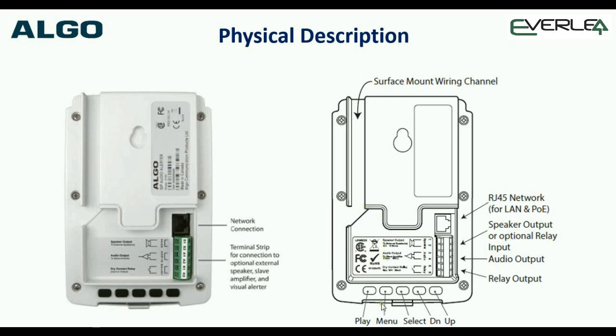The other way, if you've just plugged it in, is simply press this menu button here 3 times, and the unit will talk to you every time you're pressing it. On the third press, it'll say give device status, and then if you press select to select that option, this button down there, then it'll actually talk to you and tell you what the IP address is, e.g. 192.168.1.114, and it'll just keep repeating that until you tell it to stop.